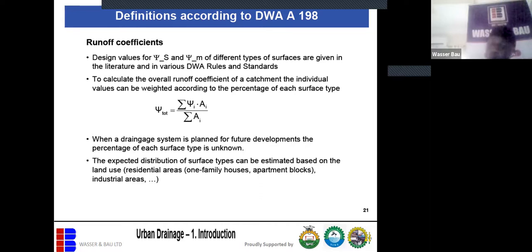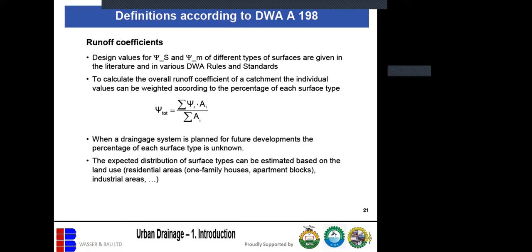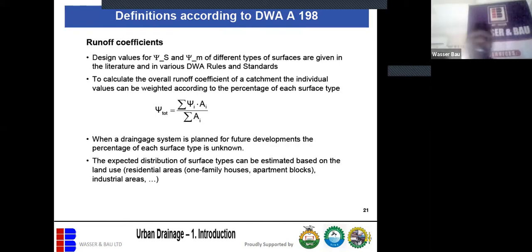If you get them wrong, if you design for a low density area what is meant for a high density area, you're going to have a lot of issues. Then if you design the low density area using the design for high density area, you're going to incur a lot of costs. So it's always good for you to ask to know what is the land use of an area. What was planned there? How many families per hectare? That will go a long way in helping you.